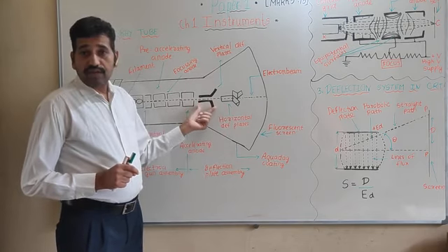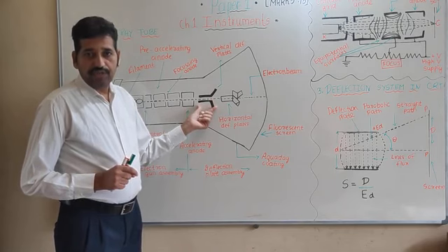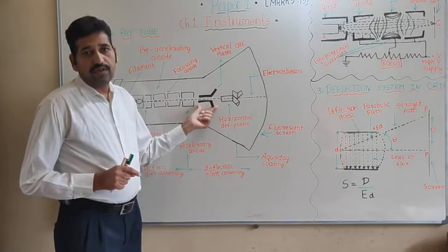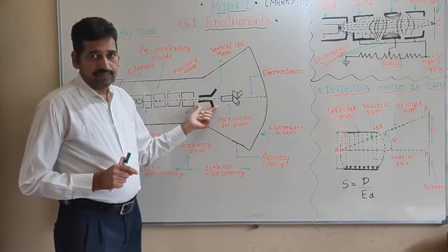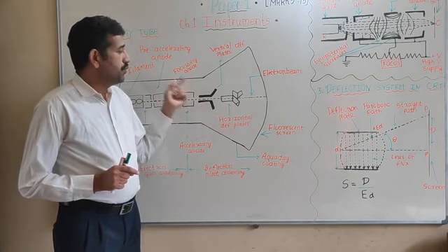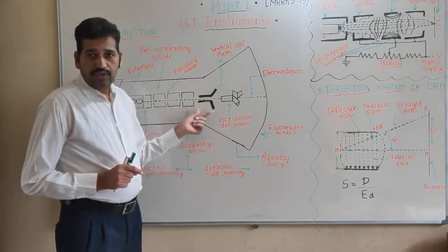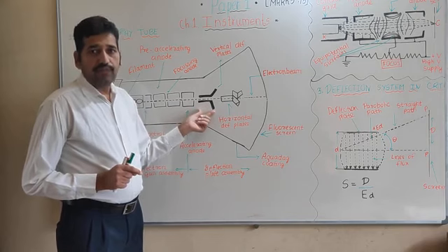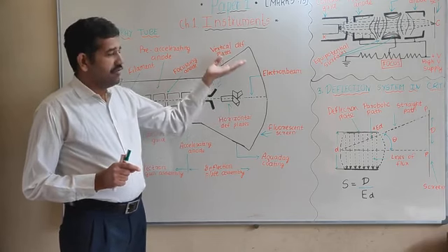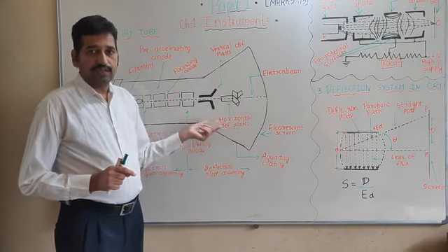Vertical deflection plates are positioned horizontally, which divert electrons vertically. According to the input voltages given to the vertical plates, the electron beam may divert to the up or down of the screen.